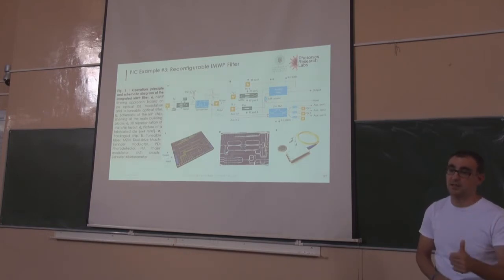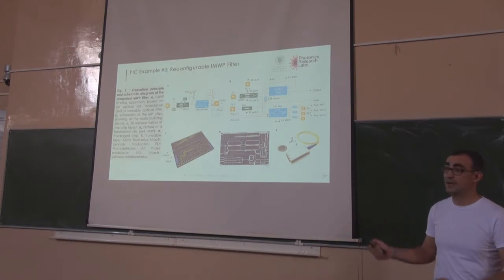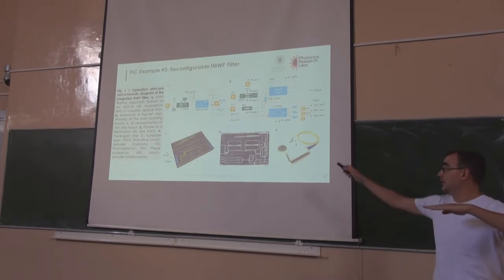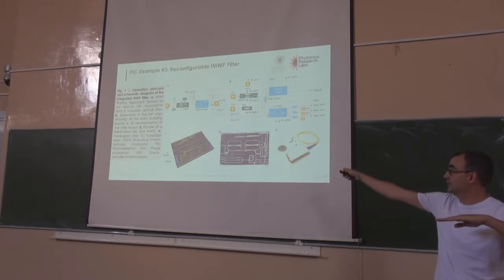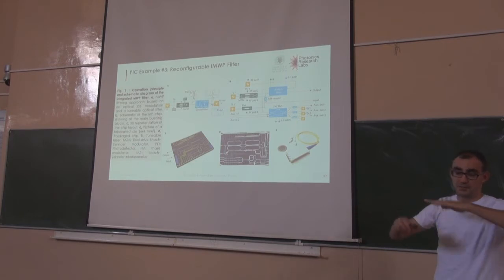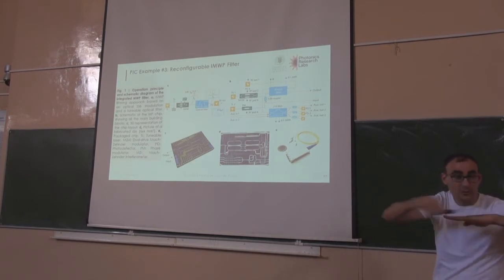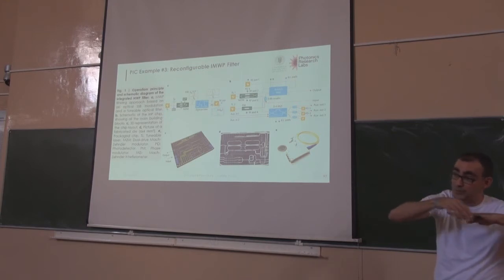One thing is polarization rotation. Okay, the lasers will emit light in TE mode. Okay, TE mode usually by convention is associated with the plane of the chip. So this is the chip, the laser is sitting on the chip, the light is emitted with polarization parallel to the chip plane.